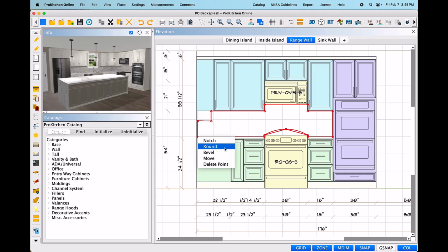The next option is Round. Once you left-click to select, you may once again only create the rounded corner to the interior. As you move the mouse, you will see a preview of the rounded corner. Drag the rounded corner into place and left-click to secure. Once created, you will now have 2 points on either side of the curve that, when selected, will change the shape of the item, and a center point that will allow you to adjust the curvature of the rounded corner.